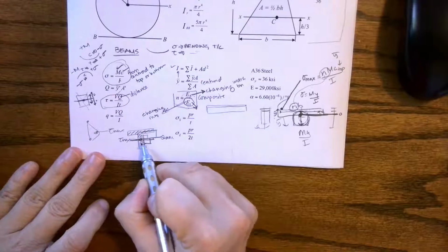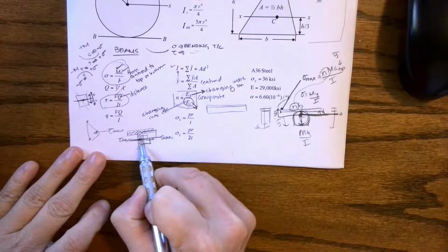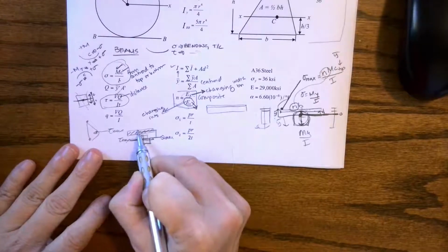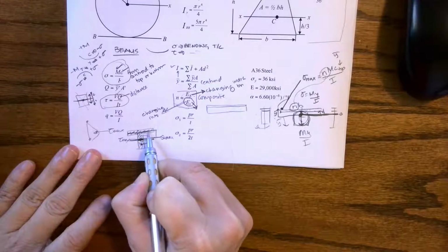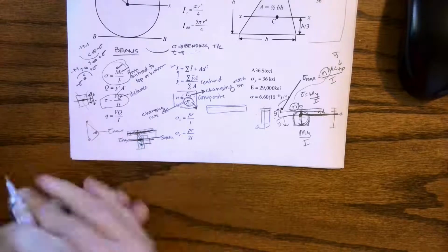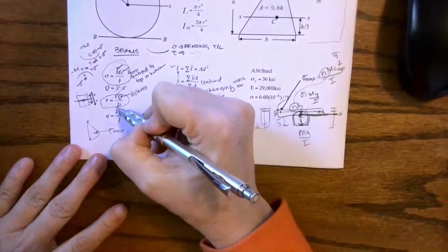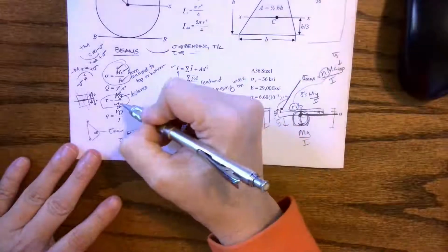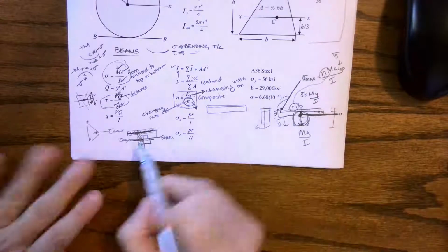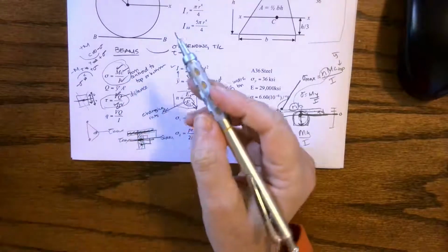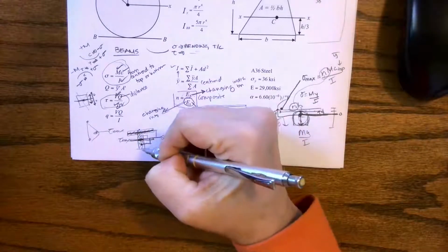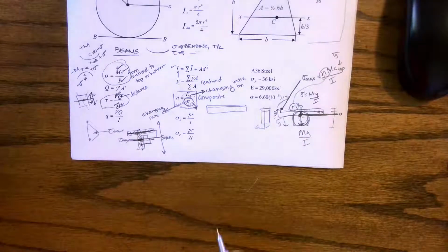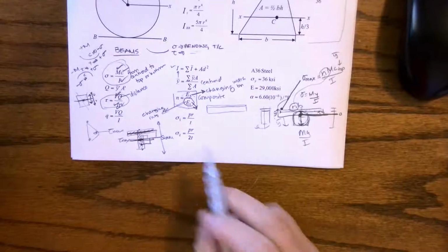Thickness is going to be the thickness of the fiber I'm looking at. If I'm looking here at my centroid, it's going to be this thickness, okay? If I'm looking here in the middle of the top part of my T, then that would be my thickness. Okay, so again, V is going to be constant for the whole cross section. I is the same moment of inertia here. t is just where am I looking for my shear stress? Q is the area beyond, which is why it's 0 at the top or 0 at the bottom, because when I go beyond the top or beyond the bottom, there's no area, so Q is 0.